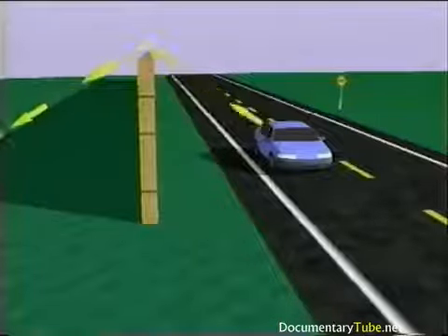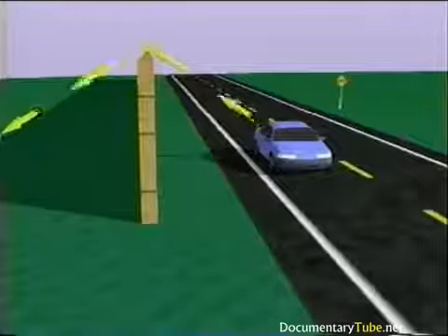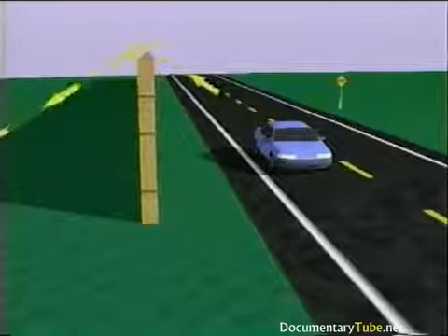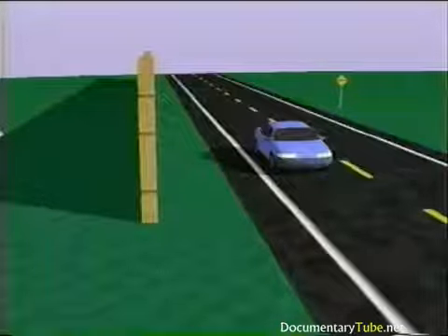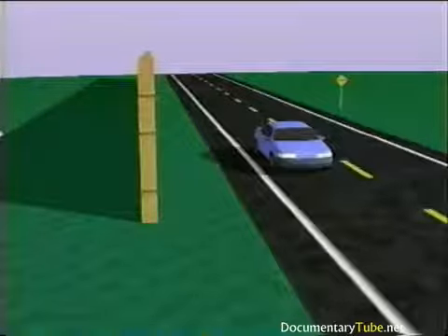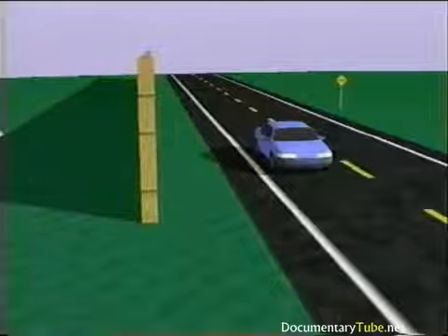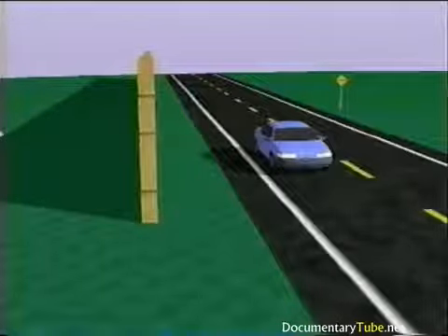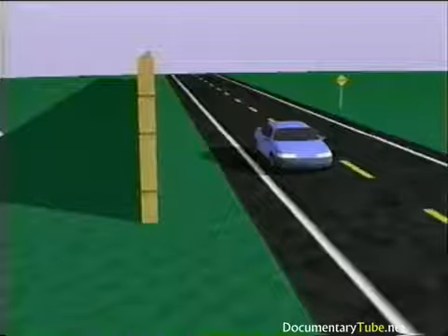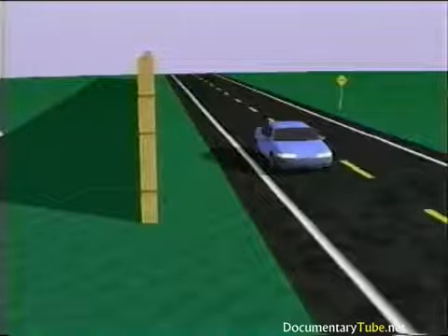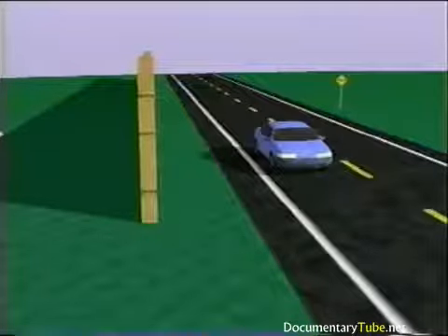The frequency content of the sound is important. As discussed earlier, there's a direct relationship between the frequency and wavelength of sound. Lower frequencies have longer wavelengths, and higher frequencies have shorter ones. As a result, diffraction is not uniform over all frequencies. Longer wavelengths that approach the barrier height easily bend over the top of the barrier right down to the receiver, whereas shorter wavelengths bend just slightly over the top, not reaching the receiver.